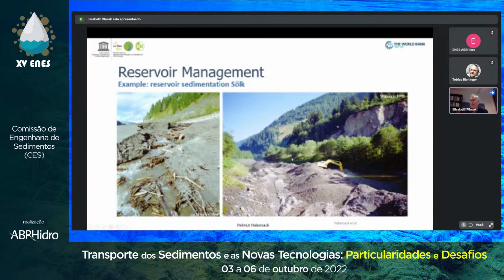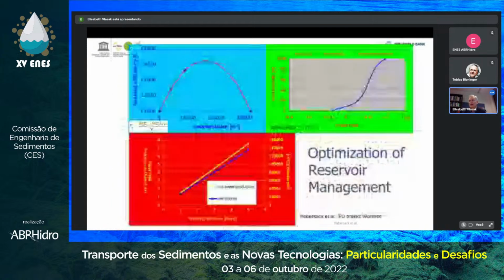But the good thing is that the coarse material does not then enter the main reservoir. It's a pre-sedimentation area, and there's a ramp differentiating the pre-sedimentation area from the reservoir itself. In the reservoir, you for sure get the fine sediments, as you see here with deposition of the material and then the trees and so on around it.